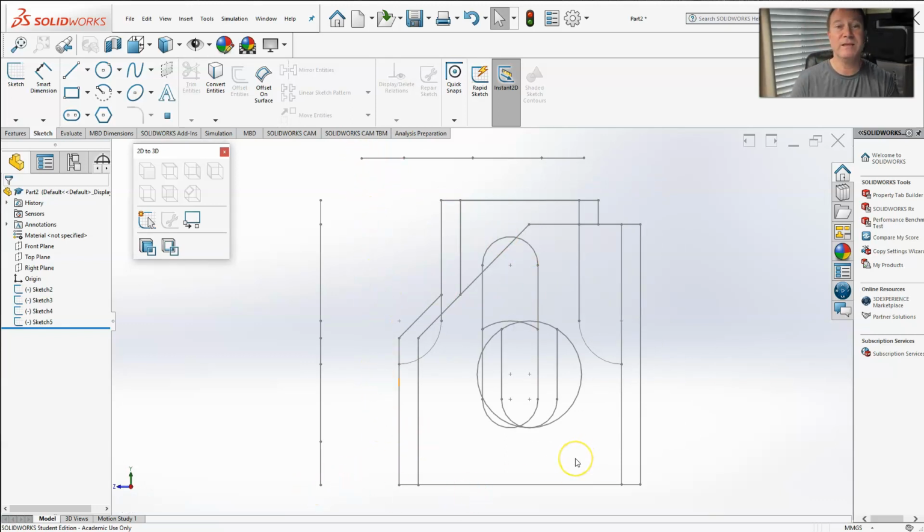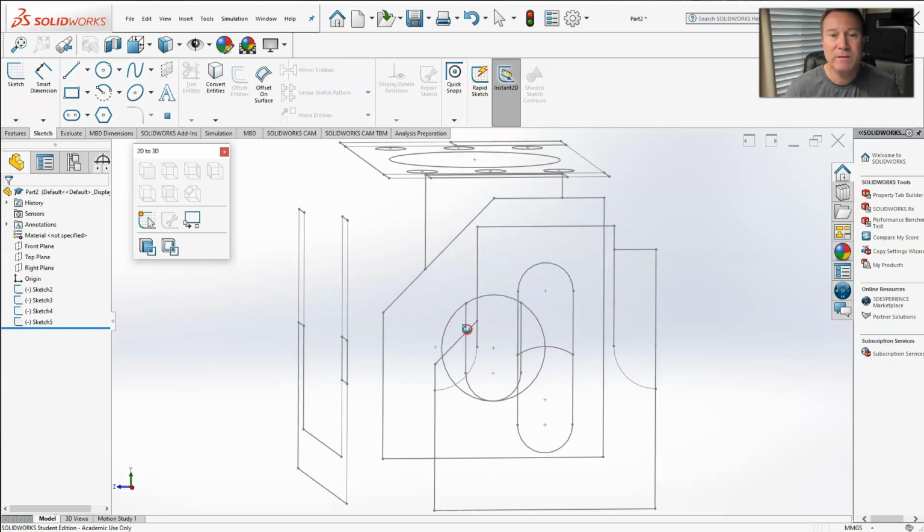Right and left, because when you fold the box out, the right and left sides will be aligned with the bottom. So is the top also. They'll be aligned with the sides. But if the original drawing didn't have the views exactly spaced the same distance apart, this is what happens to you when it rotates it. It rotates it at the same distance on each side of the front view. So if the right view is farther away from the front view than the left view is, you see this offset. So it's easy to correct.